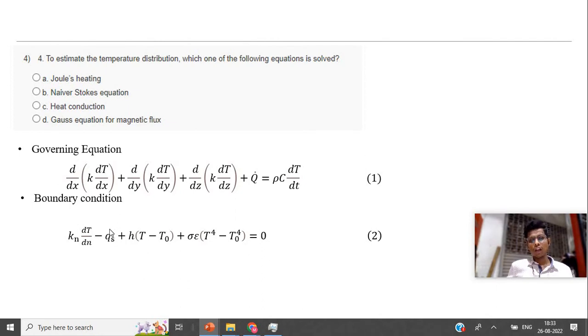If it is surface heat flux, we will use this and the other will be 0. If it is volumetric heat, then we will use internal heat generation in the simulation software, and we will set this to 0. So it's based on the process and our knowledge, whether to use this or this.